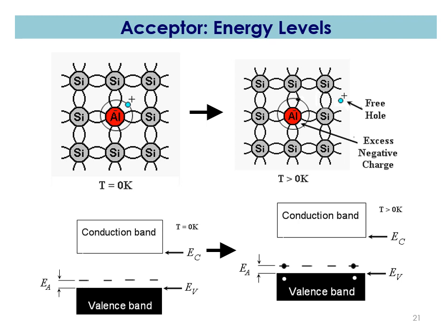And also in here we have another example of P-type extrinsic semiconductor, such as silicon doped with aluminum. As we know, aluminum comes from group 3A, which is lacking, or missing, one electron at the valence band. So the missing electron will create the hole in here.